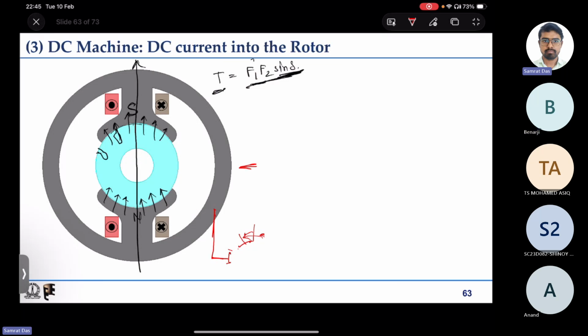And they are coupled by some magnetic field. That means you could represent it roughly by two EMF sources, because EMF will be there in both the windings, some E1 and E2, connected through an inductor. The coupling can be represented by the mutual inductance.